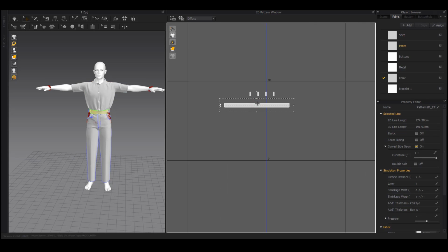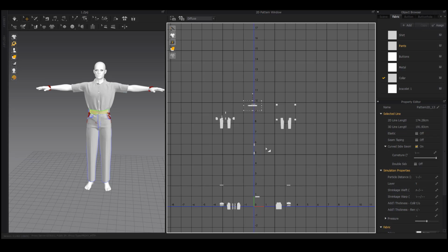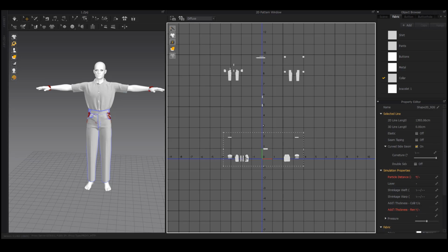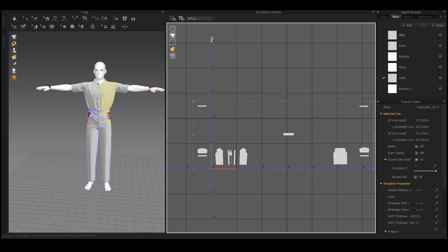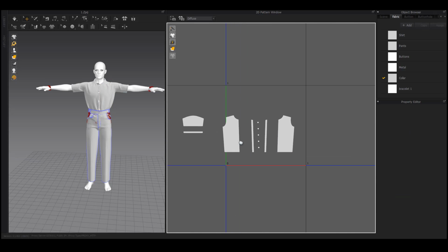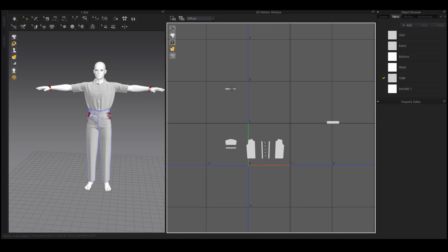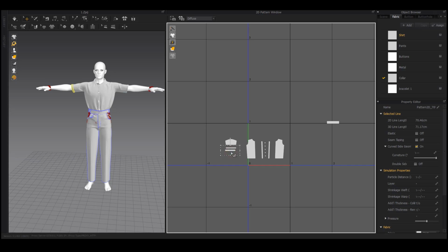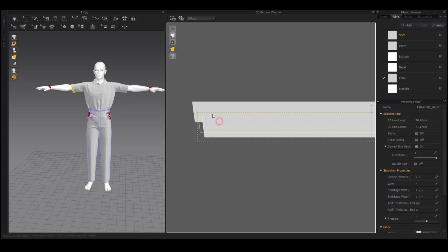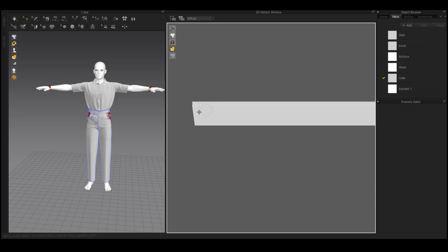To do this, at the top, change the toolbar to UV editor to enter the unwrap toolbar. So far, no automatic unwrap tool has been added to this version of Marvelous Designer, so we have to manually place each of the clusters in UV. There are several things to consider. If symmetrical paste was used when making clothes, it is necessary that when making UV, the bonded clusters should be completely mirrored. Otherwise, when making the normal material, the fabric in that series of parts is made in the opposite